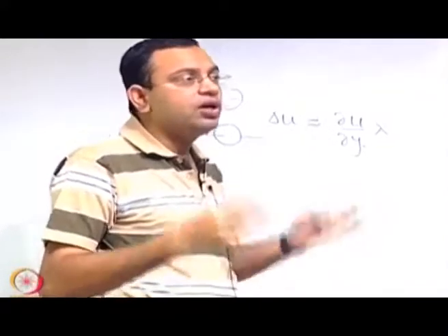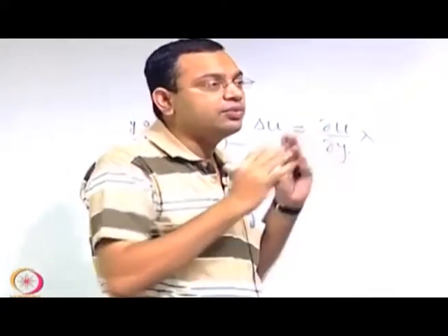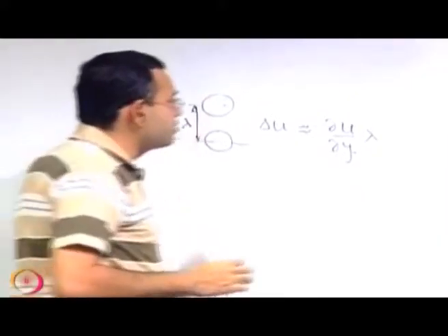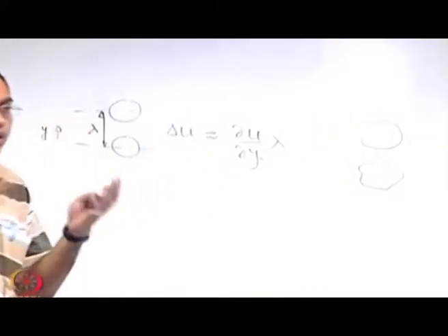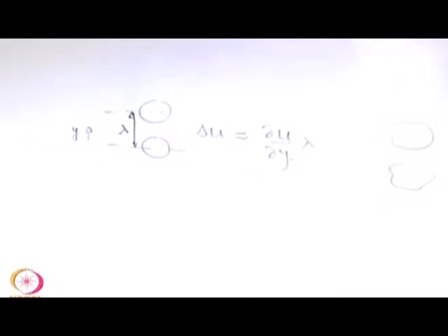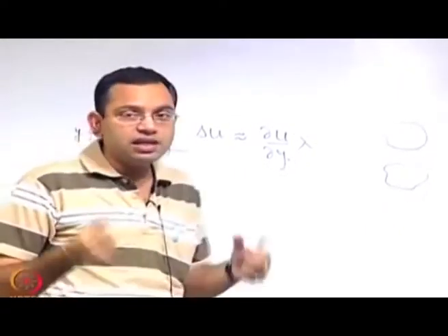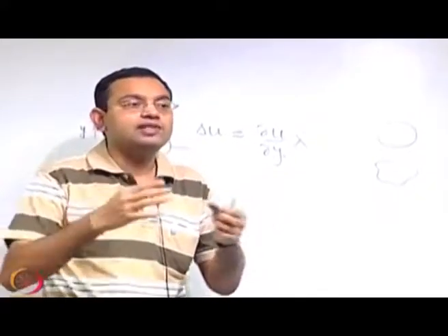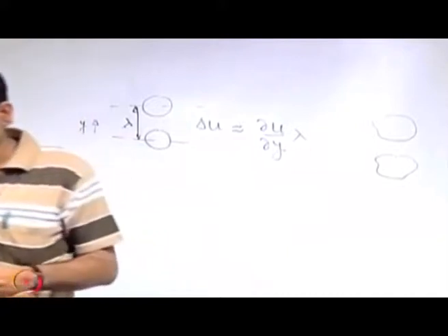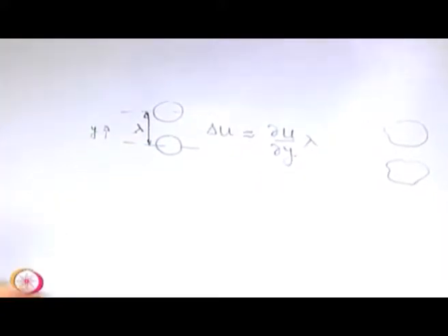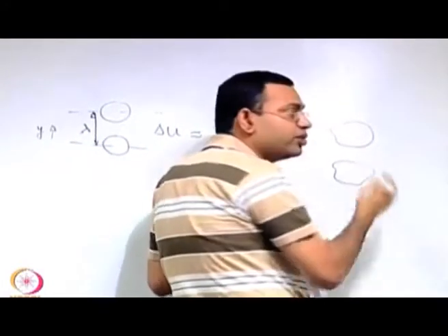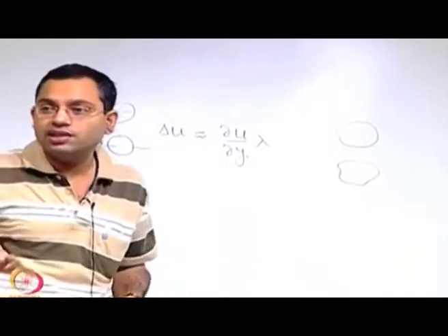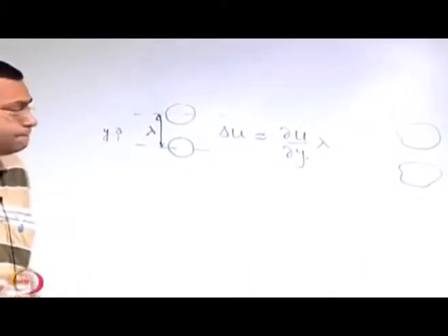Now in turbulent flow the molecular picture is not important, it is just the analogy that we are drawing. Now imagine that instead of these molecules we have interacting eddies, which are lumps of mass with some sort of rotationality, some sort of vorticity. So in a turbulent flow basically there is a chaotic advection of vorticity with respect to position and time. Vorticity is one of the very important issues in turbulence. So these are strongly rotating structures. Whatever it is, these have random fluctuations in their velocities, just like they have u prime, v prime, w prime, like that.